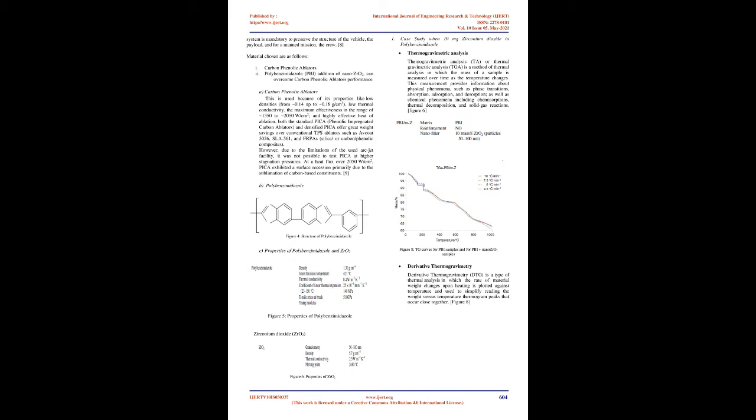Surface emittance should approach unity for maximum heat dissipation. Materials that gasify completely exhibit excellent heat blockage, therefore all of the initial solid material should be converted to gaseous products. A high ablative temperature is generally desired for conditions involving a very high heating rate. The converse is true for a low heating rate environment. To summarize, the ablative performance of a material may be altered by many different environmental variables. Careful consideration should therefore be given to each of these factors in determining the performance of a material, and in selecting an ablator for a specific high-temperature environment.